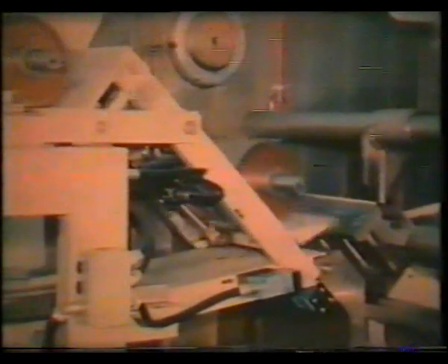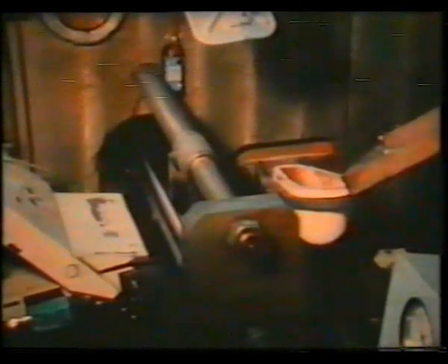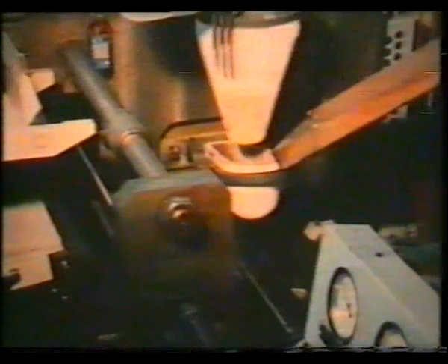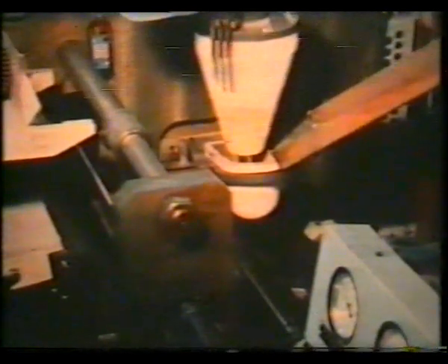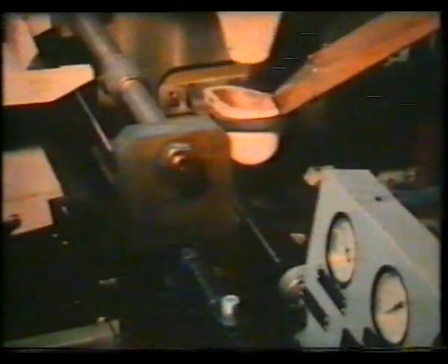The front stack is singled out and reaches the loading prism. It is then pushed through the fixed machine platen into the moving die half. On completion of this motion, the machine closes and is ready for casting. The valve of the ladling device opens. The molten metal flows into the filling sleeve and is instantly injected into the die.